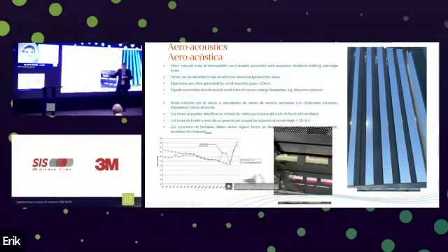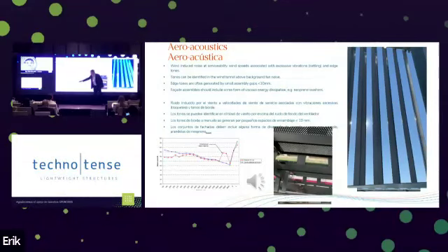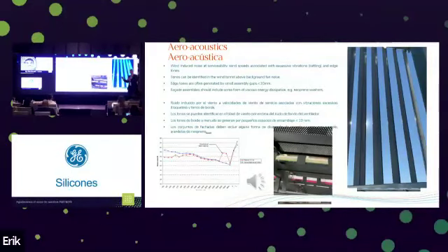This is a wind tunnel test on a sample, a perforated sheet. Now you can basically hear the wind tunnel and then hear this tone coming in. It's about 5 to 6 kilohertz and it's sitting above the background noise. Now, obviously, we don't want that on site. So much better we test in the wind tunnel first before we actually go and assemble and install on site.